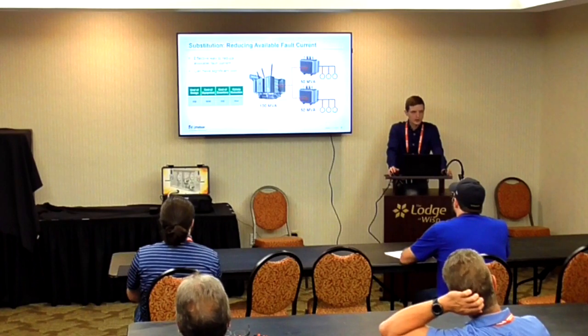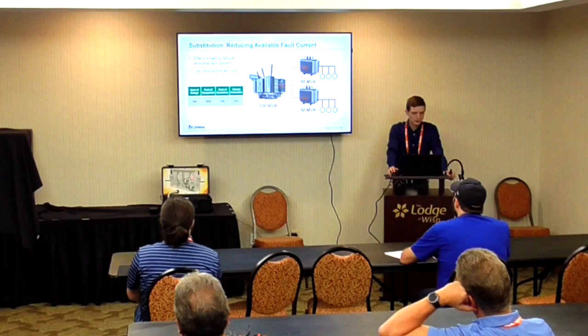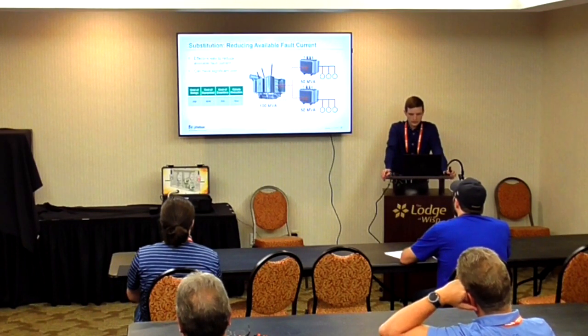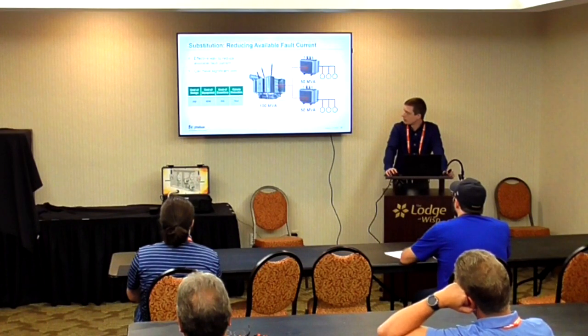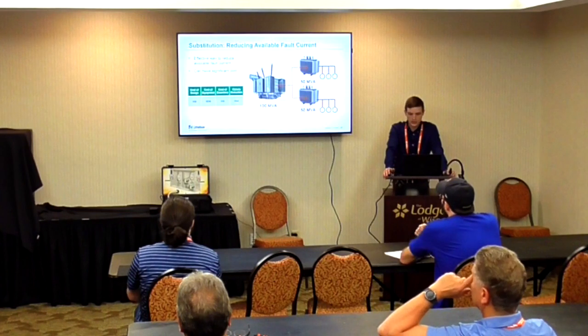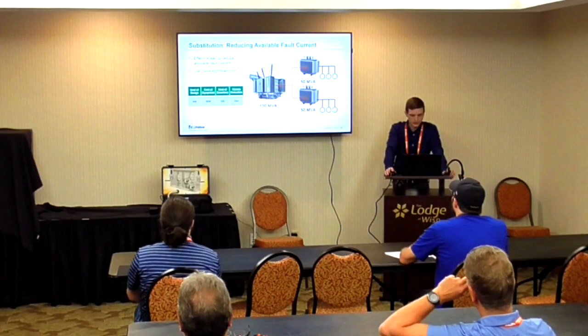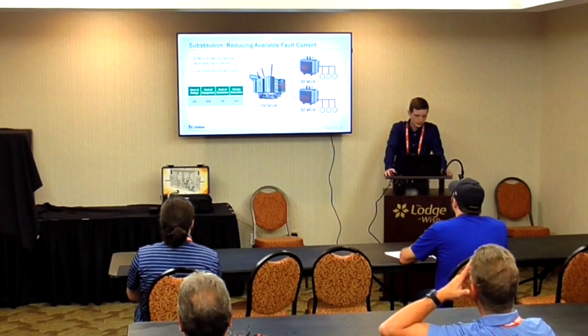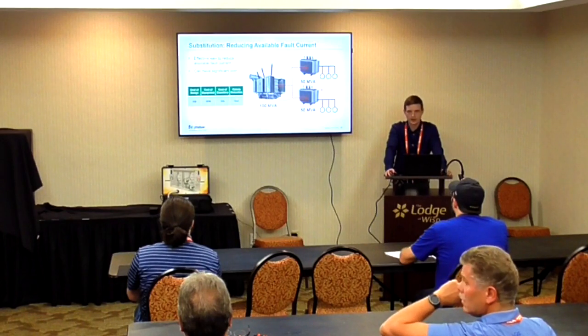First one, which is right near the top half of that hierarchy of controls, it's the second one on there, is substitution. So this is the actual idea that you're going to change a very large transformer over into smaller transformers. This is something that you'll typically only do at the design phase, because as we know, transformers are very expensive, something to the tune of millions of dollars. So essentially what you're doing here is you're cutting your incident energy effectively in half.